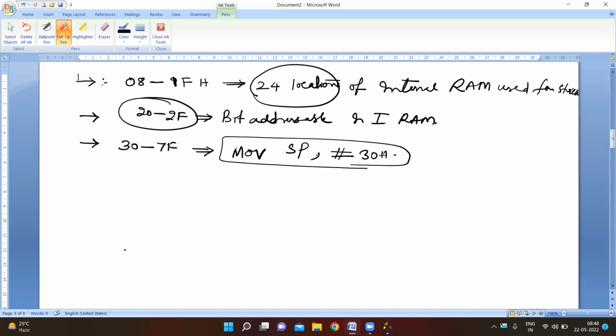Next, in a program, the number of pushes and the number of pops should be equal. In any program, while executing the subroutines, the number of push instructions should equal the number of pop instructions. And this is very, very important. Otherwise, our main program cannot return exactly to where the call instruction ended in the main program. Therefore, the total number of push instructions in a program should be equal to the total number of pop instructions.